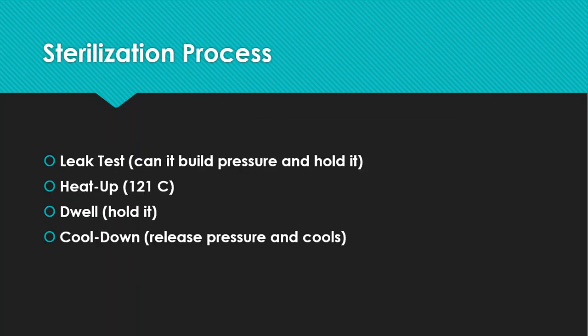Sterilization process. Again, high temperature, high pressure. So there's a couple of things that you want to make sure happen here with sterilization. Number one, you want to perform a leak test. And the reason is because if it can't hold pressure, it's not going to be able to fully complete the sterilization process here. So can it build pressure up, and can it hold the pressure that you have set?